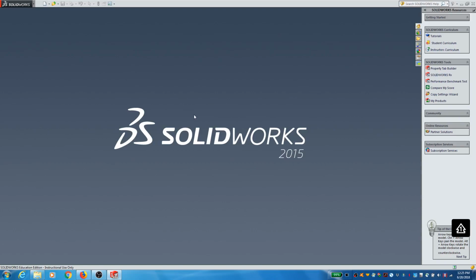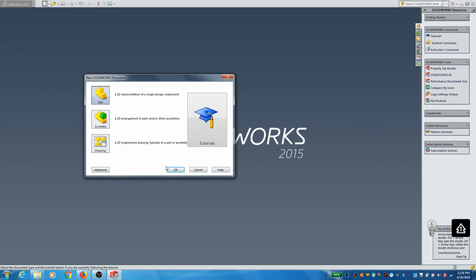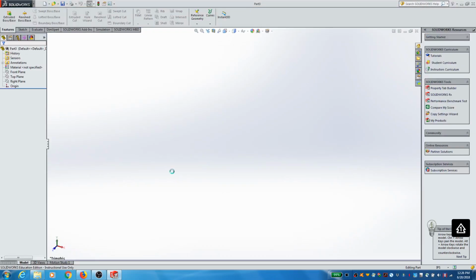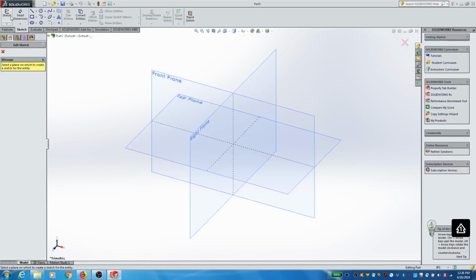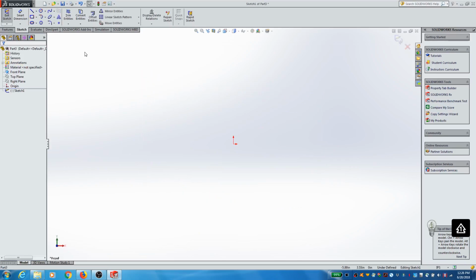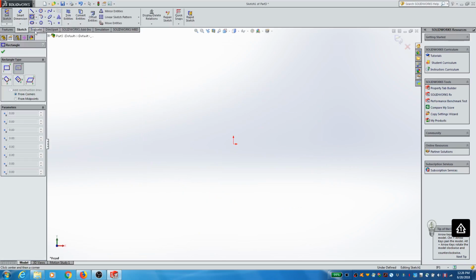We're going to ask to see that you can master each of these concepts by building a simple part. All right? First thing we're going to practice is an operation called shell. So I'm going to start by creating a new part, just like we did before. And I am going to first sketch. I'm going to pick the front face. You guys know my habits now, right? I'm going to start with a rectangle. I'm using a center rectangle tool to do my sketching.